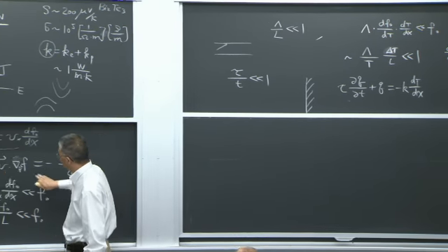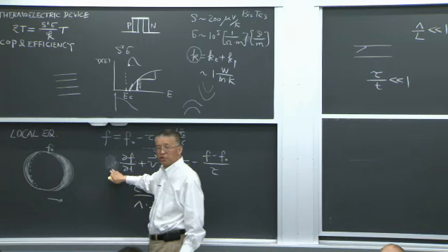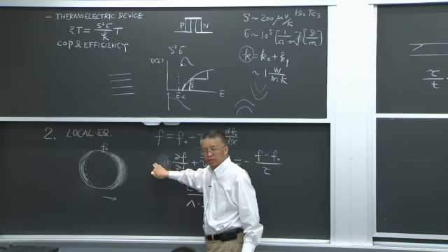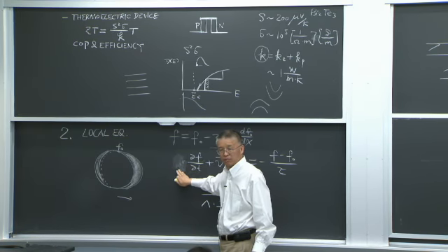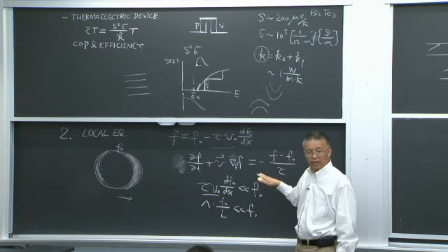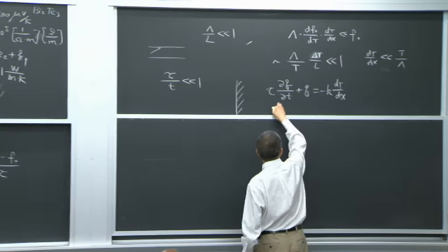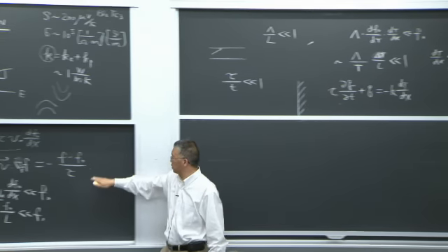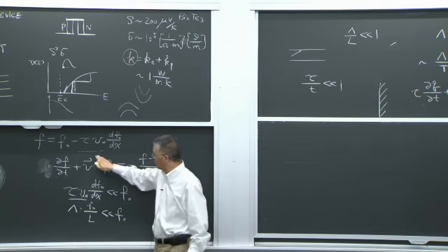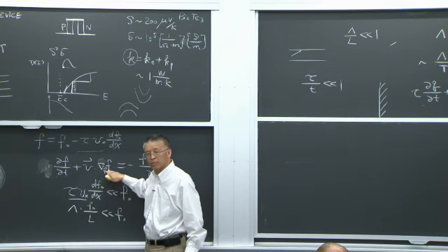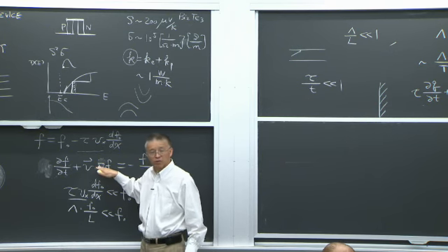So you put a tau on this side, and you integrate times the velocity times h omega times the density of states. You integrate both sides, and you will actually get this term. That's this term here, and this term you approximate still with the Fourier law.